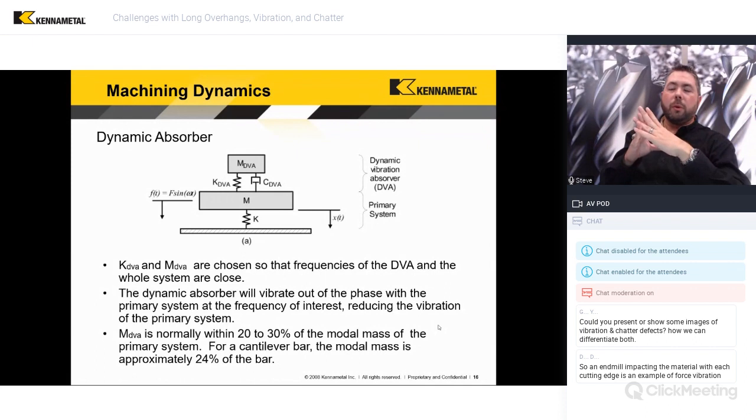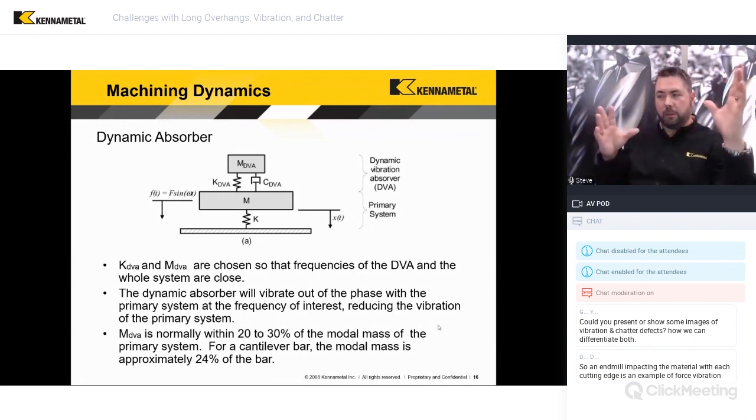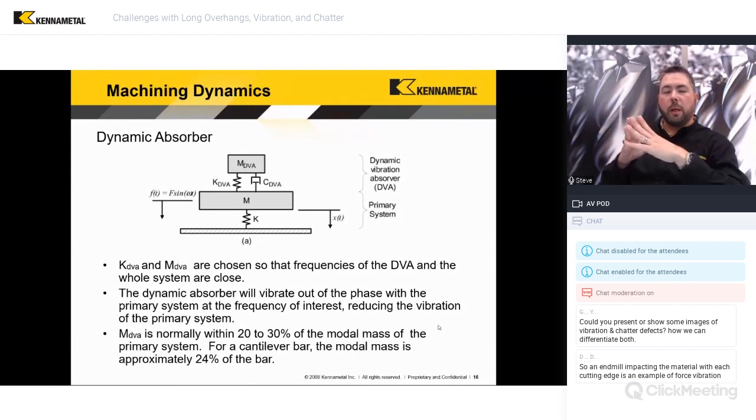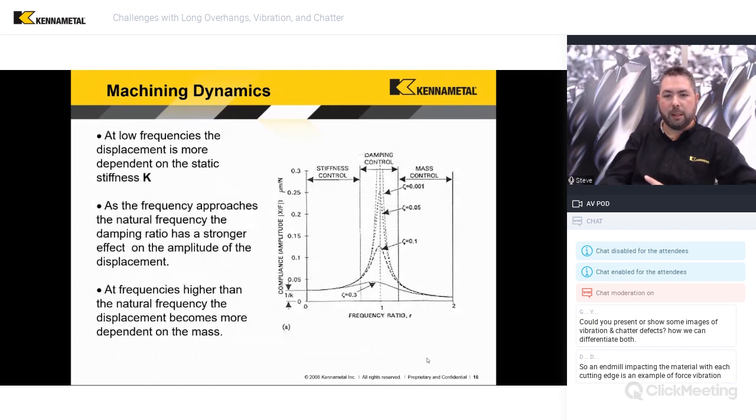So we basically come down to three parts of this balanced equation. One is the spring element, against displacement. One is the damping element, which is against the velocity it's moving at, and then the mass itself that we're dealing with, along with acceleration. Those three elements help counteract the forces that we apply and help us calculate this. This is going to be really key to our topic today as we break down how vibration-free boring bars work, some ideas of how to use them, and how to troubleshoot them. So we'll come back to this.